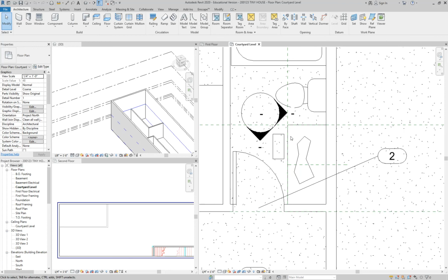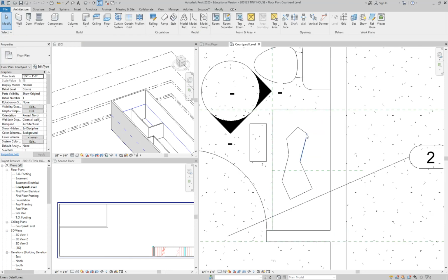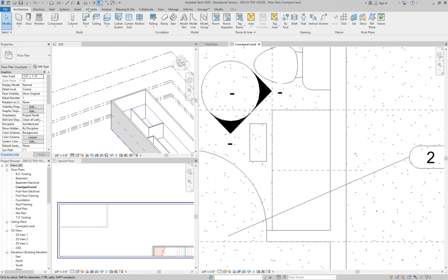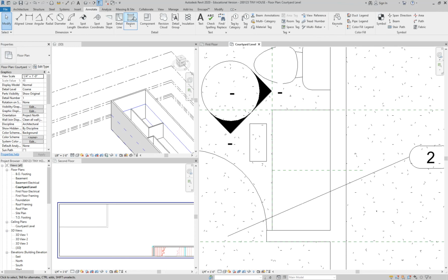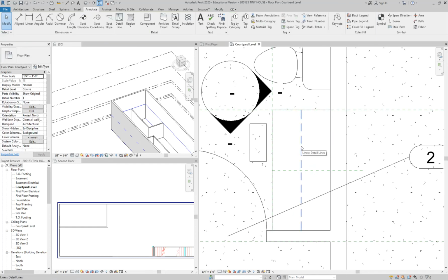So that it looks right? I would do your whole counter, pretending this is in the kitchen, and these are detail lines. Let me delete those. What you could do is come back to annotate, grab another line, but make it a hidden line or overhead, either one. Oh, that's what I was missing. And then there's your dash line to show the upper cabinets above. Brilliant. You could do it that way.